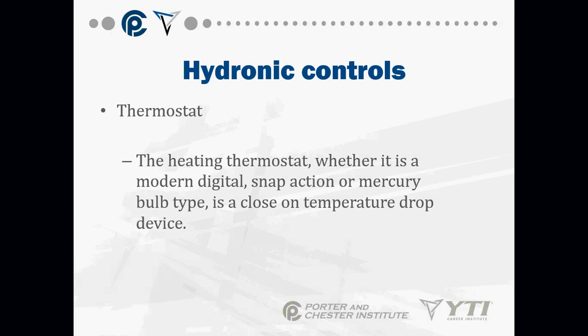If the boiler temperature is too low, it will tell the burner to come on so that I can now heat the water, so that I can now deliver heat to that wonderful space to keep this homeowner so nice and toasty warm and happy. So you will find that with a boiler, the way things operate is really not much different than on a furnace. We're just typically adding 1, 2, maybe 3 more components into it.